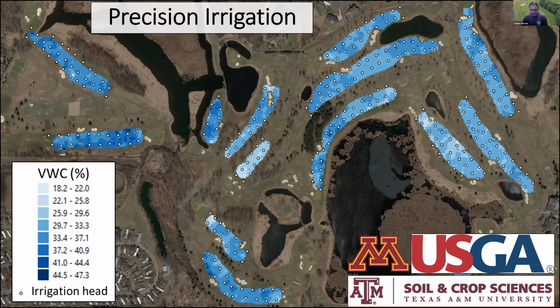So if you time your data collection correctly, which I typically recommend after a rainfall, whenever you bring your soil moisture up to near field capacity, you have that uniform application of water, so you're eliminating any kind of deficiencies in your irrigation system when you collect your data. Then you go out, you collect your soil moisture at that time, and you have this nice map from near field capacity conditions that will really highlight your underlying soil conditions.